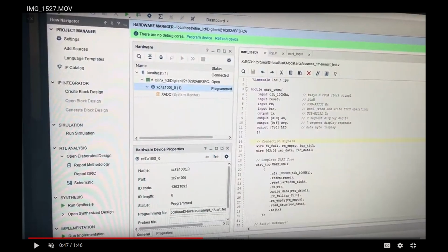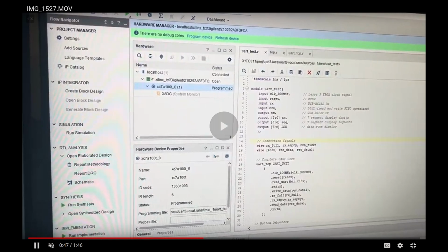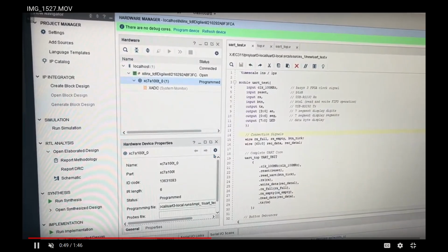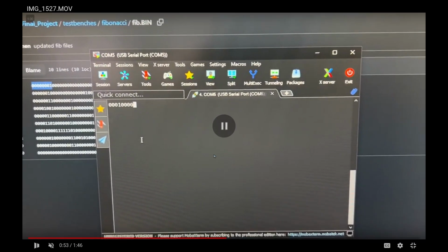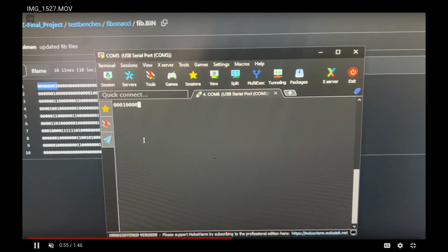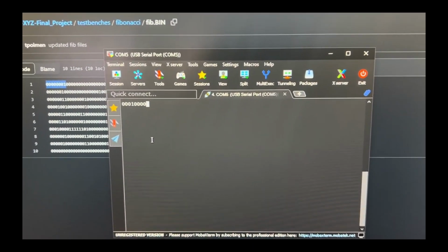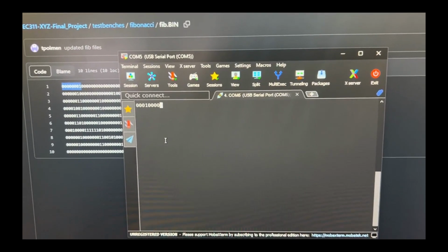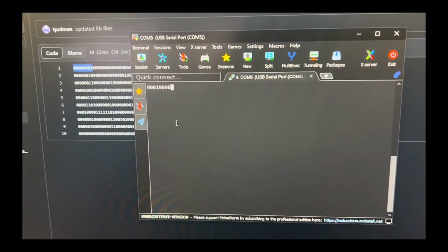We more so used a quote-unquote test bench source because it's hard to use TX and RX. You can't really do that with a test bench. So instead we use this provided UART test. And you can see here that we input the values, and then the buffer wasn't fully flushed, but you can see that it does output values that were read into it.